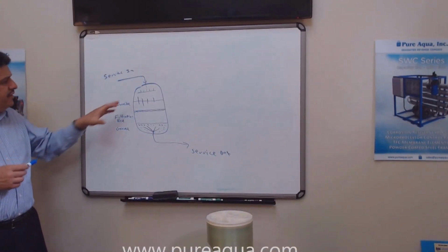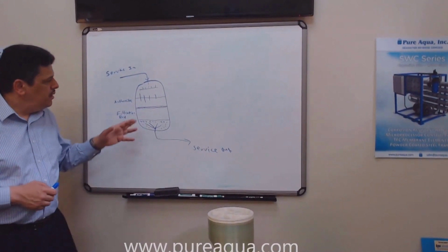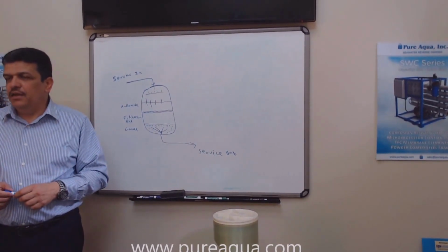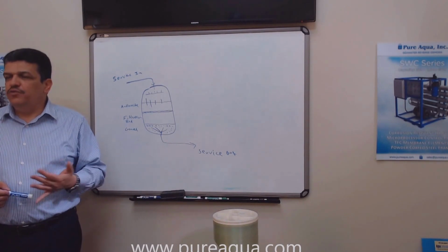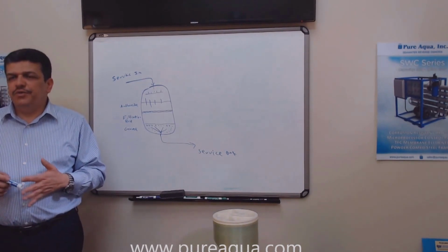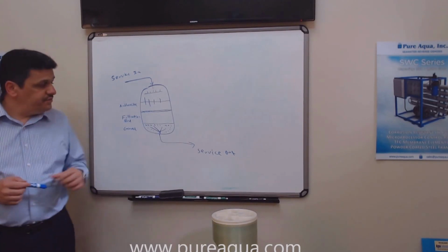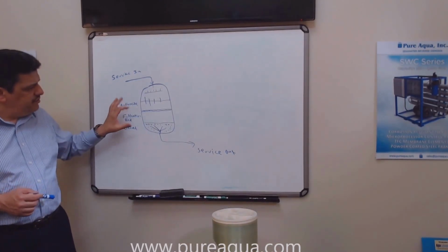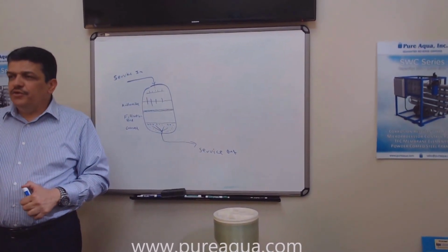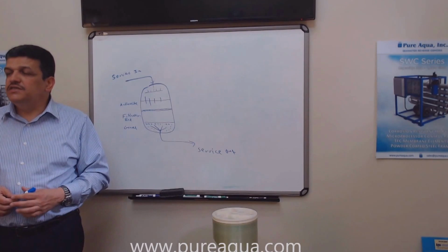The second thing, after the water goes to the filtration bed, like what we already compacted right now. Most people use the standard number 20 here, which is a fine filtration bed. It does a good filtration. It will filter suspended solids, particulates, turbidity. The good thing about the media filter is we call it a depth filter. About 30-inch depth here. I mean, the minimum should be 24-inch. It removes the very, very fine particulates. That's what we call silt in water treatment definitions.